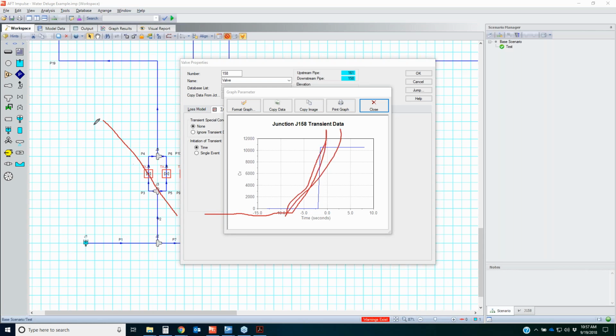Okay, so the slope of this curve will dictate how high those pressures get to be, based on the time that you close over. If you watch one of my previous webinars on surge suppression, you'll see a valve closure example where instead of closing it linearly, you close it part of the way really quickly, and then the rest of the way over a longer period of time. That's what we call the 80-20 rule.